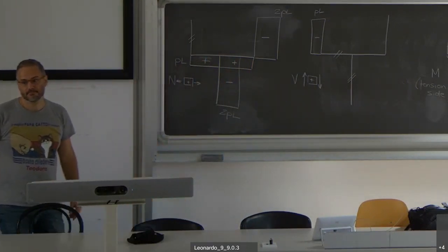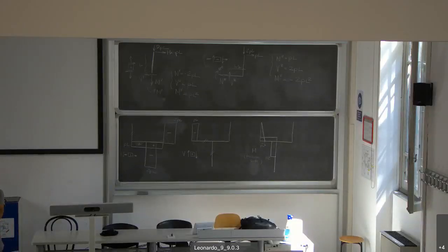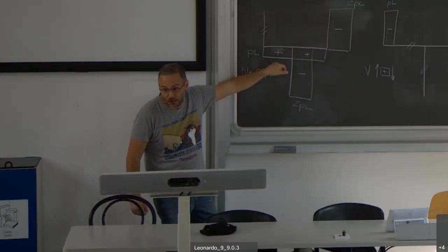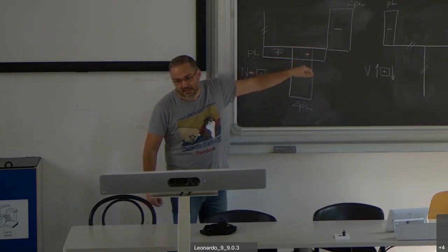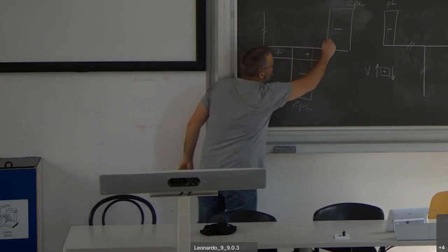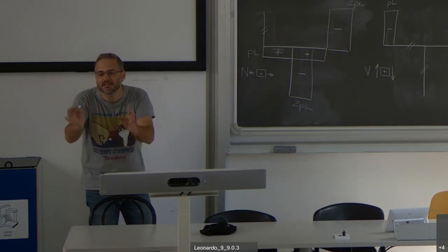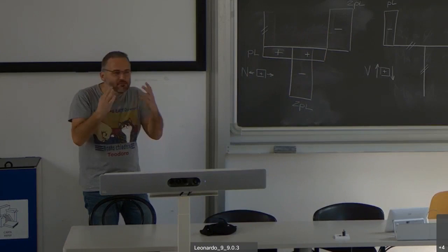Okay? Tell me. When you plot the negative sign of the shear force, can it be on the other side of the line? As I said previously, the important thing is that if on this half it's positive below, on the right side it's positive below, okay? So I shouldn't make positive below, and then above. It makes confusion. Although it's not strictly incorrect, it's simply confusing.